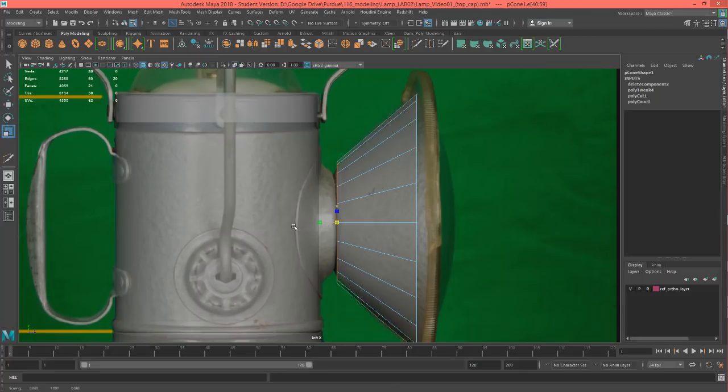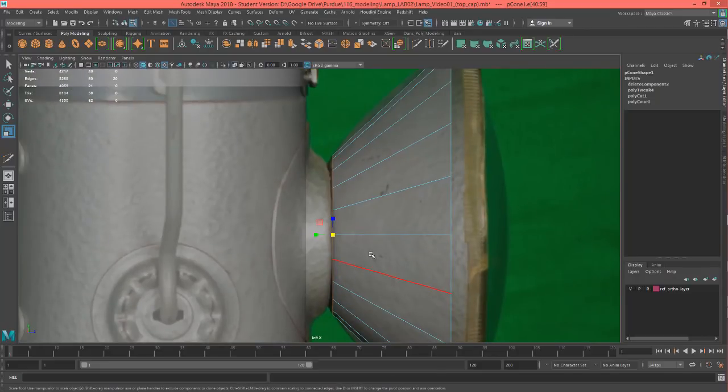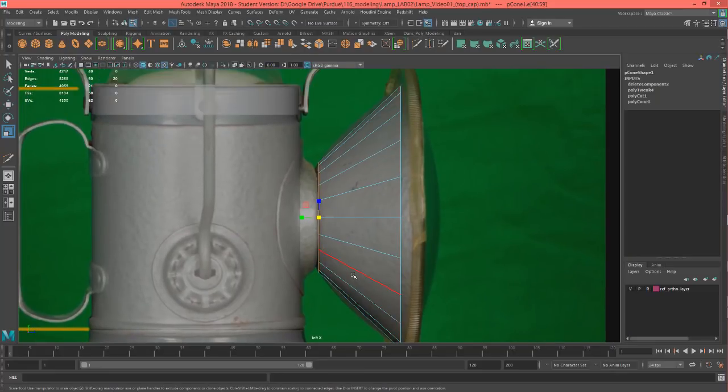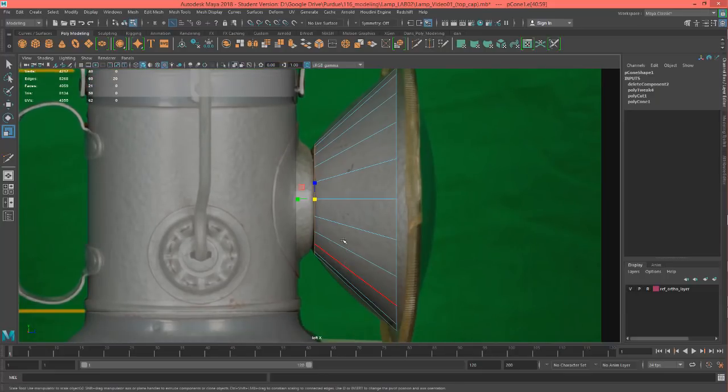I have my 1, 2, and 3 keys on my keyboard set so that 1 is verts, 2 is edges, and 3 is polys. And then I actually use my F1, F2, and F3 keys for my smooth preview. So anytime you hear me say I'm going to hit 3 on my keyboard for smooth preview, I'm actually hitting F3. I'm telling you that because for me personally, it works better because I can switch between my modes faster. Normally, F9, F10, and F11 are your verts, edges, and faces, and that just takes too long, personally. Okay, so now we should be able to cut an edge loop in here, and I'm going to